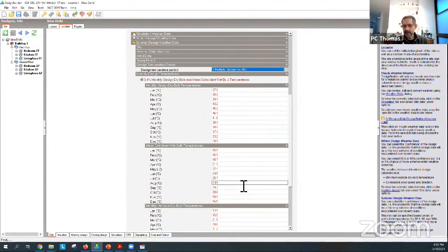If you know what you're doing, you can size your chiller block load, which is your diverse load. You can actually size air handling units. You can put different zones on one air handling unit, and it will size the air handling coil. You need to know what you're doing, but you can do that. And you can also size the zone level equipment. So VAV boxes, active chilled beams, fan coil units, you can do all of that.